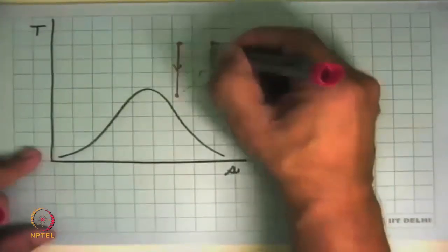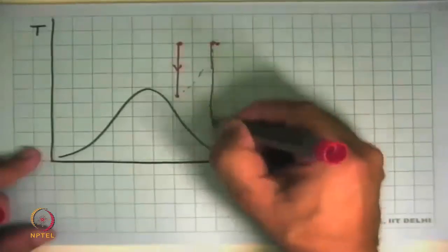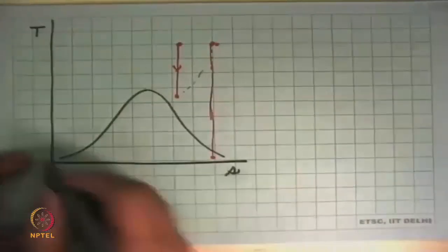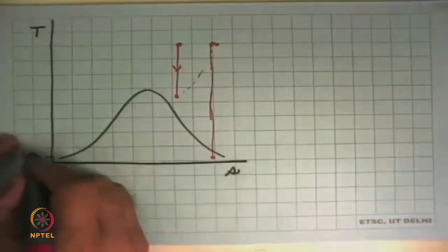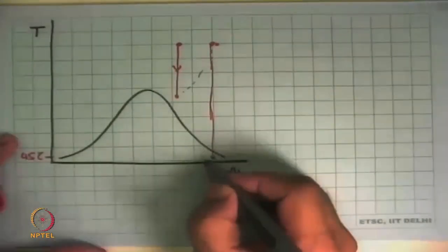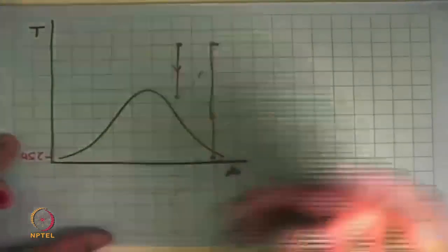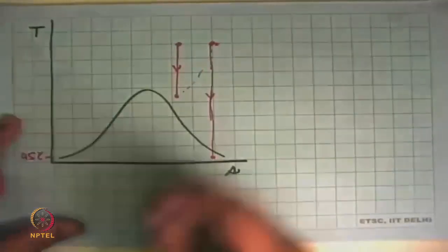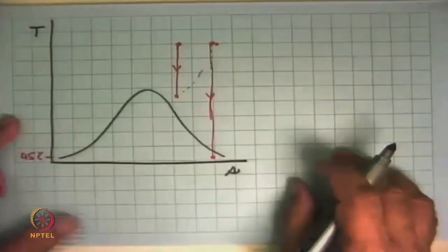Then we start expanding it in not just one turbine but multiple turbines until it gets to the temperature that is there for us, 45 degrees Celsius or so, slightly wet steam at the end of the turbine. That's where we have to be careful about the engineering of it. So that's what power steam turbines would do.